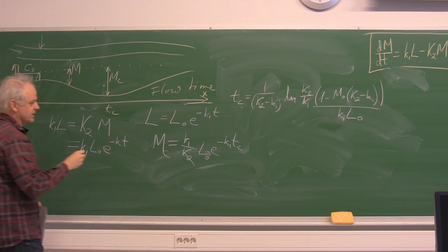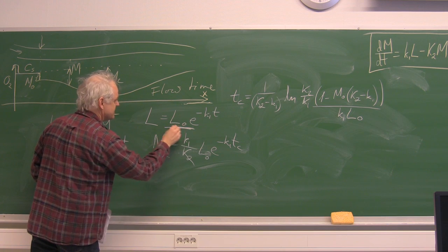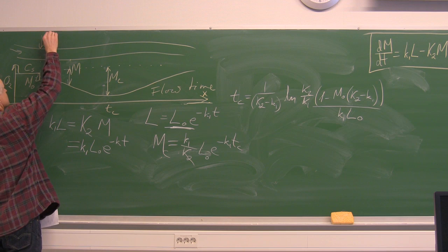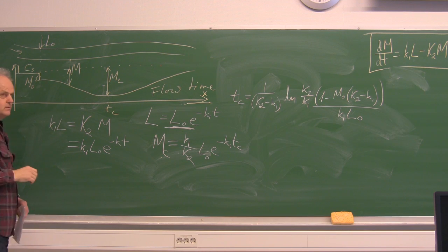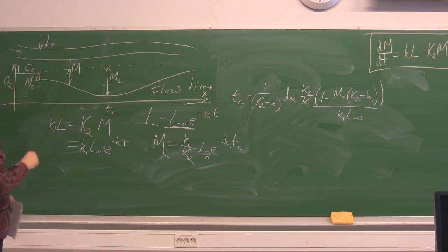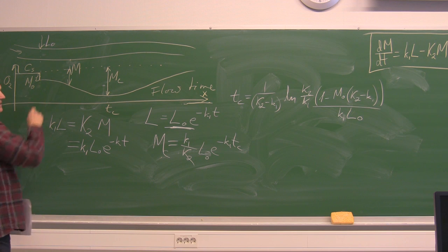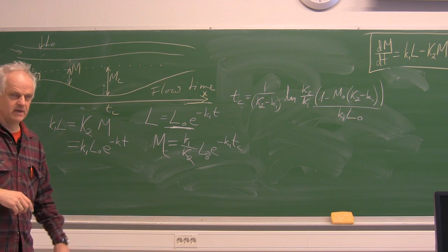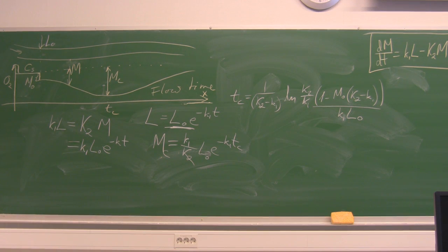The important one is the initial BOD at the discharge, which is essentially where L0 is. After it's mixed here, we find L0. Okay, that's the theory. I'll stop there in case there are any questions.